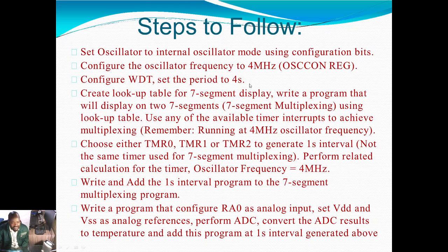Some parts of the system will still be functional until one has figured out what is causing the problem on that section of the program and solves it. The watchdog timer is useful to ensure that the system never gets stuck. If it gets stuck, it automatically resets so that at least minimum functions that are functioning correctly can still continue